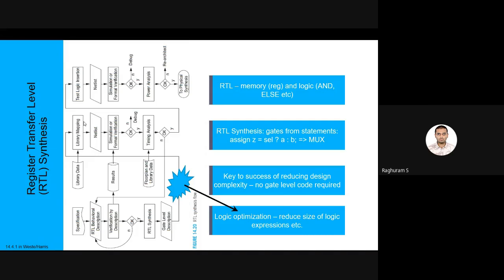You can have behavioral blocks. You can have blocking statements, non-blocking statements. You have a lot of functionality. And this functionality is designed, I mean, whoever designed the language is aware of the requirements of a digital design. Because without that, there's no point in designing a hardware description language. The language has to describe hardware, right? So whoever designed the language, they knew that.